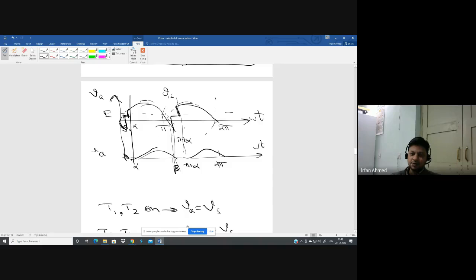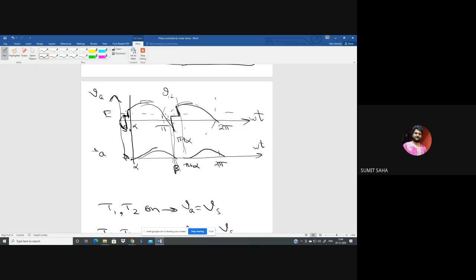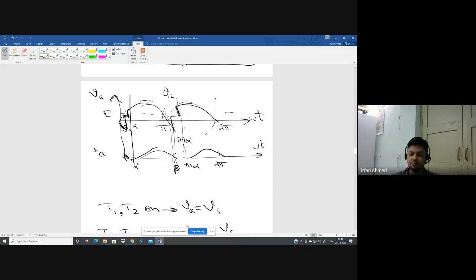And for continuous conduction, the limit is beta equal to pi plus alpha. Okay, so beta is not 0. If inductance is 0, beta is theta 2, or beta is pi if there is no back EMF. And for continuous conduction, beta is equal to pi plus alpha. Okay, so beta first of all depends on the value of the inductance.